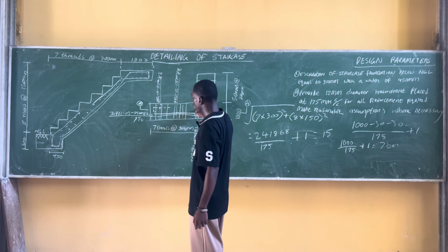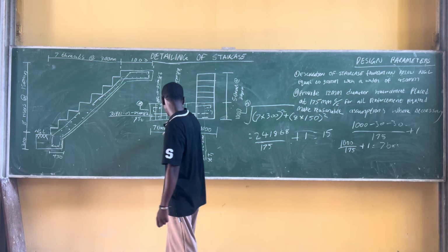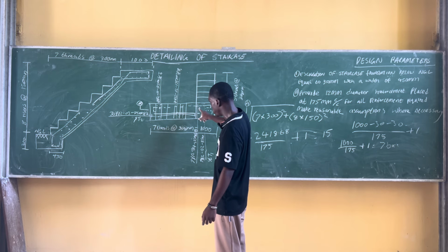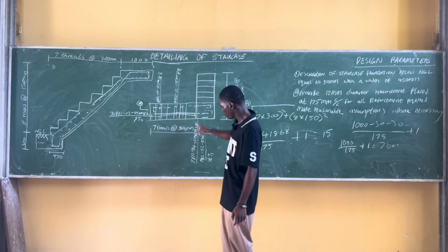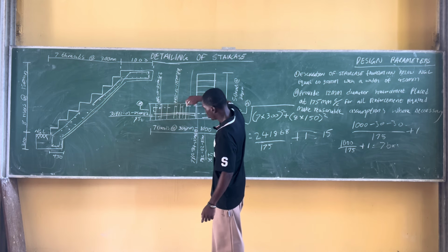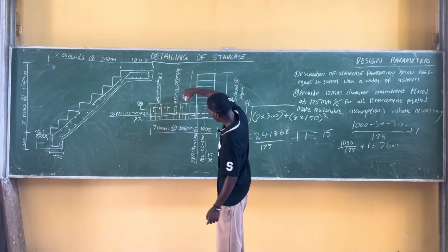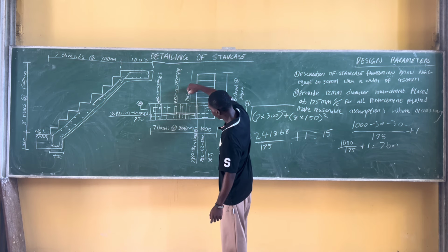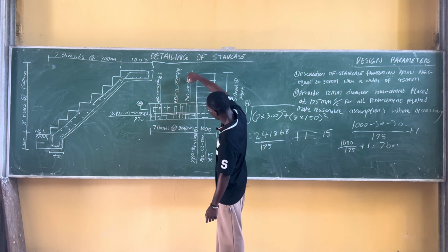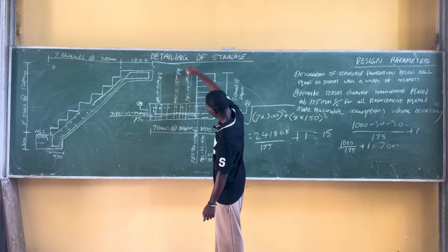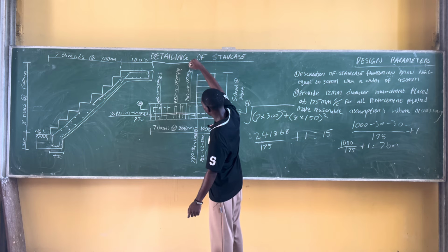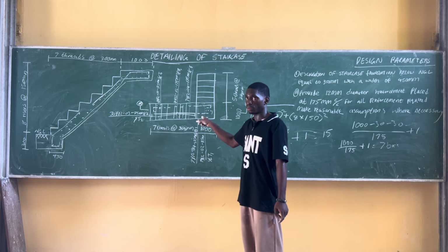Now this is our top. Okay, this is our bottom reinforcement. We'll turn to a top reinforcement here. So we're going to put a dash, dash, dash, dash. And it will still be the same thing. The bar mark will be the same as this bottom reinforcement. And the bottom reinforcement will go to here as bar mark 4. But if you draw out a colored line indicating that this top reinforcement, which is here, will still be 7Y12 at bar mark 4, at 175 mm center to center, T1. That's how we got the top reinforcement for this.